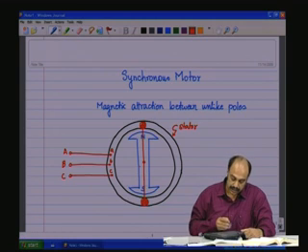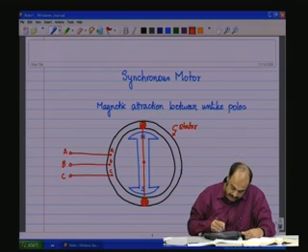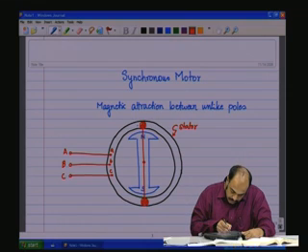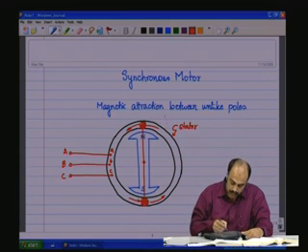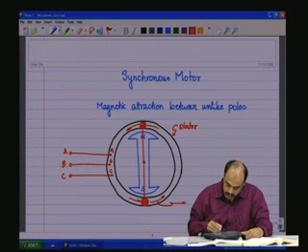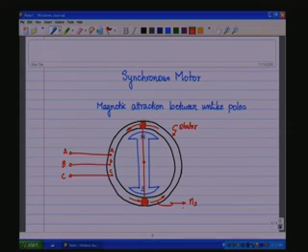So an imaginary magnetic field is produced. Let us say we have this which is rotating. And we have the dumbbell, which is the imaginary magnetic field, which is rotating at what speed? It is rotating at speed ns, which is given by 120 F stator by P, the number of poles per phase. Exactly the same as the case of the induction motor.